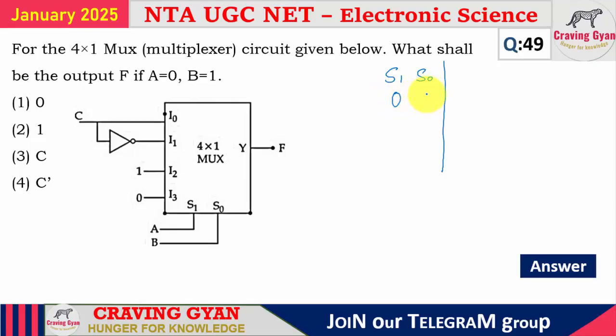If S1 and S0 values are 0, 0, then output Y is driven with the I0 input. When my select line values are 0, 1, then the I1 value will be driven to the output. Similarly, when the select line is 1, 0, then the I2 value will be driven to the output. When the select line inputs are 1, 1, then the I3 value will be driven to the output. So you will be having 2 power n inputs, n select lines, but only one output.